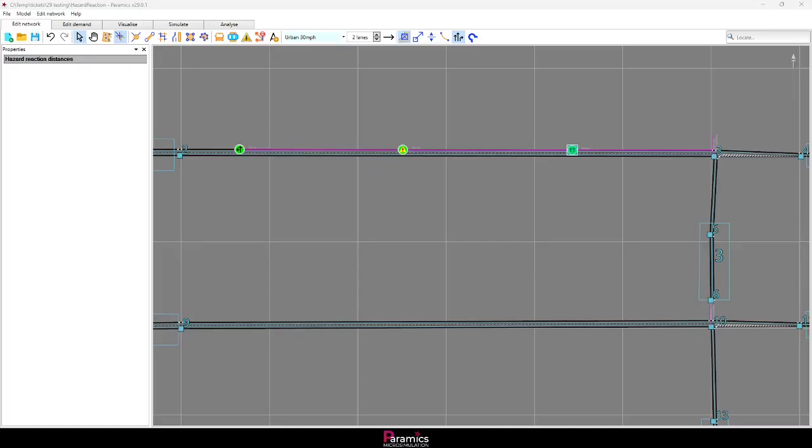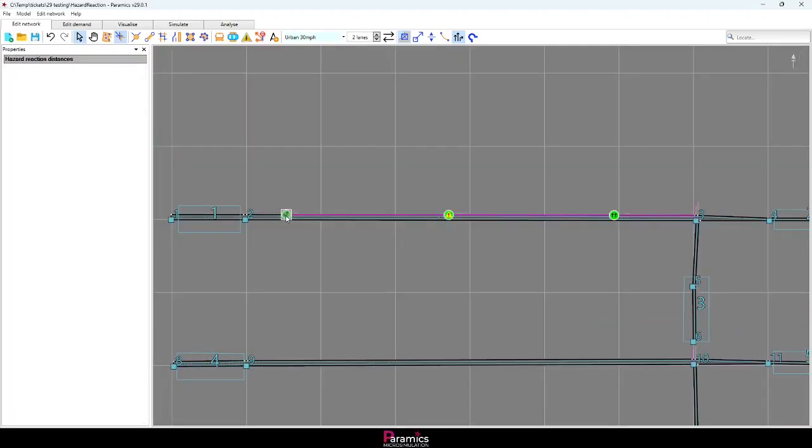You can choose the ratio between the non-urgent and urgent reaction areas to define the point where all vehicles will start to react urgently or not. Here we can set the reaction distances so that the least aggressive vehicles will start to react early, and the most aggressive vehicles will wait until very late to react.